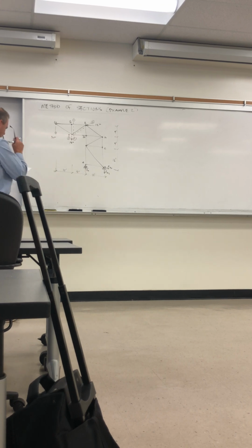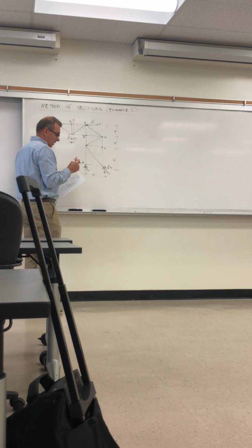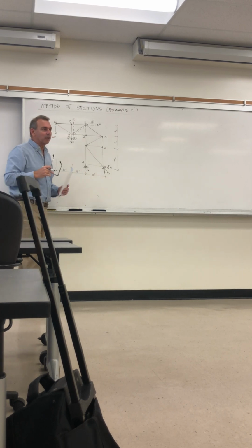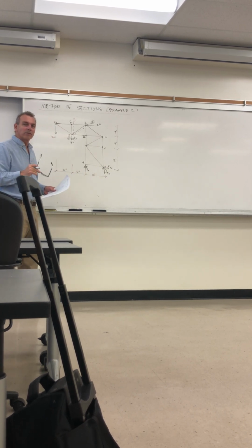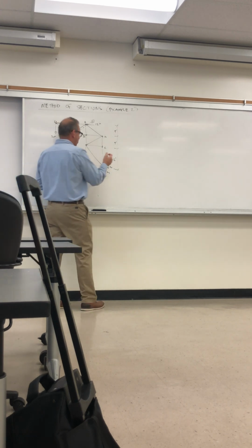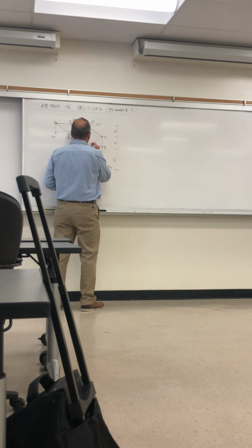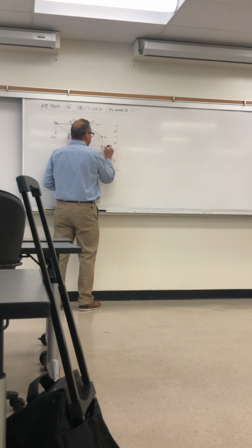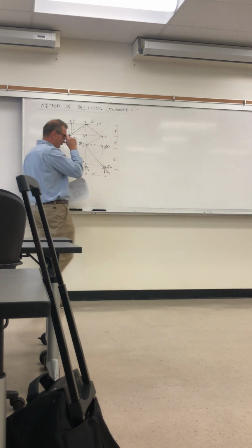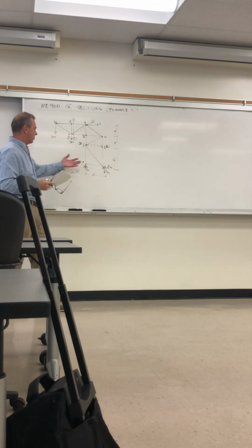And then for section 3-3, instead of a vertical or a diagonal cut, we'll take an exactly horizontal cut through the structure right above J. Here's J, and C. So this is 3-3. And in that case, we're going to have to include all these reactions.